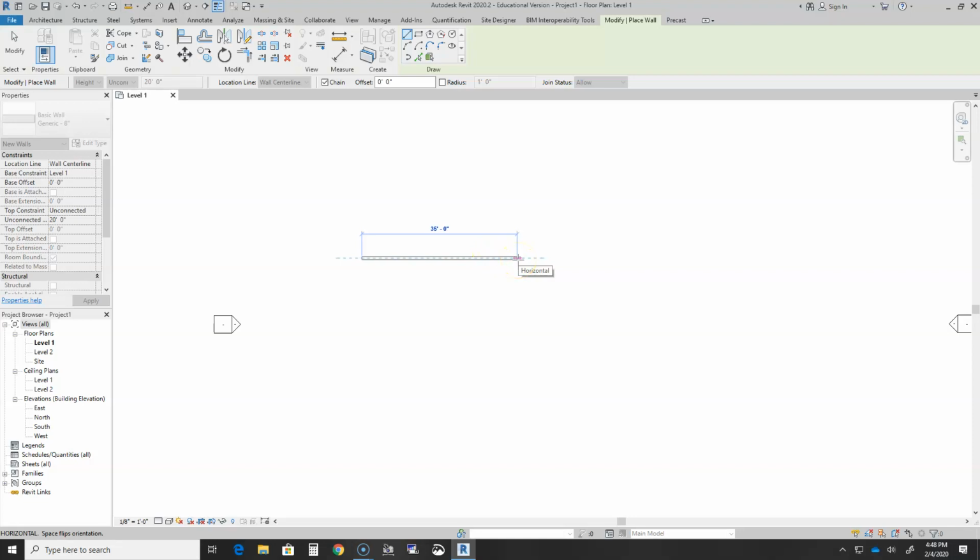Another thing to remember, and this is going to be good for your Revit certification, is understanding the direction in which Revit draws. You can draw in any direction in Revit, but Revit likes to draw in the clockwise mode, meaning that I would draw my building starting this way and then going around this way in a clockwise manner. That way, the exterior side of your wall and the interior side of the wall are in the right place. Exterior usually has weatherproof type material on it.